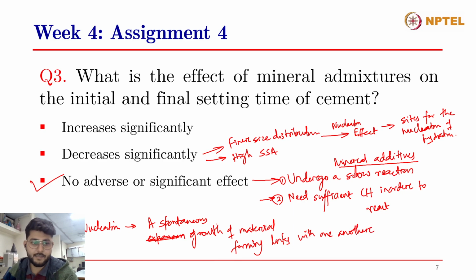So basically, these finer materials with very high surface area act as sites for the deposition of these hydration products, and thereby the formation of these links leading to the nucleation. And when this nucleation effect comes into place, so this is the site, and these are the hydration products getting nucleated over them.